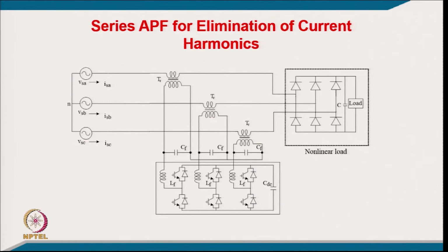Another function is the series active power filter for elimination of current harmonics. You can see here a 3-phase series active filter with an injection transformer, and I was mentioning that it can eliminate the harmonic currents of a voltage fed kind of load. So, this is our diode rectifier with a capacitive filter, which is a voltage fed load, and here we have another parallel load, maybe an inverter fed 3-phase induction motor, or even a brushless DC motor or a PMSM after this inverter.